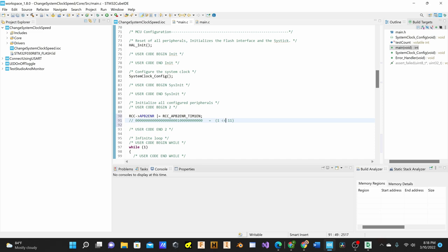We're not going to be getting into complexities like this because there really isn't any need to do this unless we start to use functions, and I show you in more advanced tutorials, like I did in the previous series, how to set certain data pins of the LCD or something like that. But we won't be doing that for a while in this series. So I'm going to keep it as simple as possible. We don't have to worry about this stuff. All we really need to know is what bit we're affecting, and it's the timer 1 enable bit.